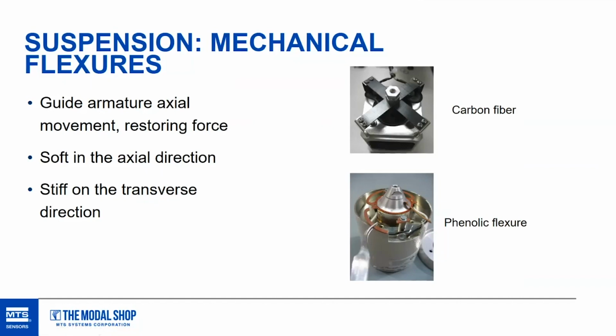They're relatively easy to break, especially because if you're mounting things on the shaker all the time, you're applying some torque on the whole armature. That torque is transmitted to the suspension system, and eventually you can have a small crack, and as you're shaking, that crack over time, we end up having a failure on the suspension system. So the carbon fiber materials are nice.